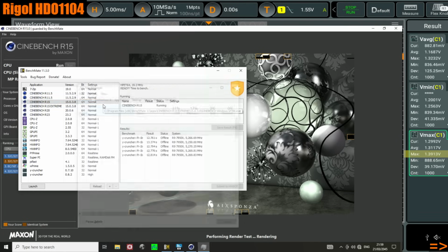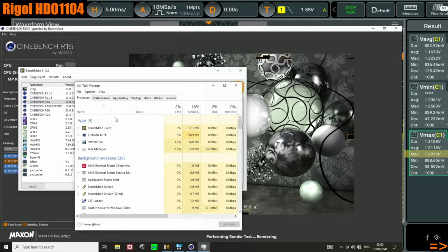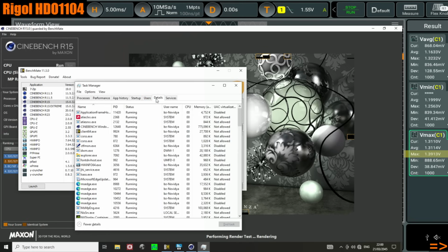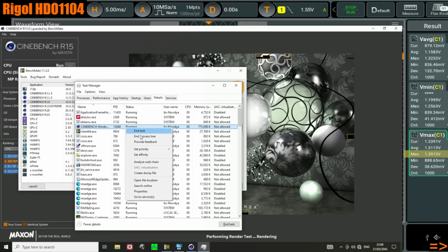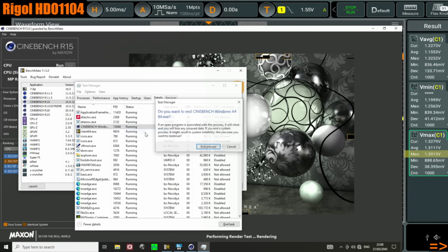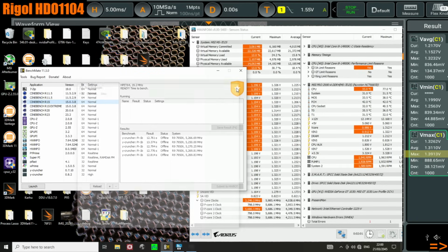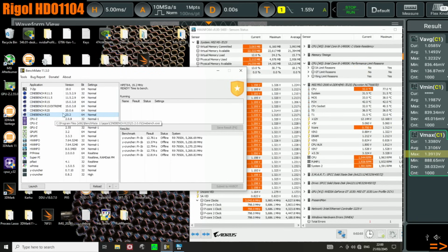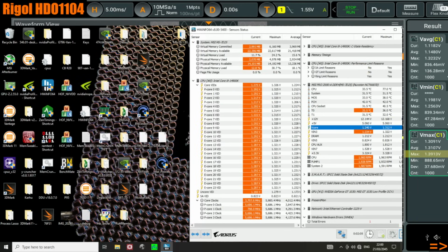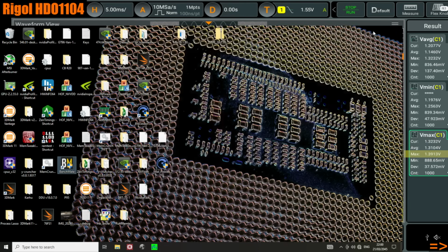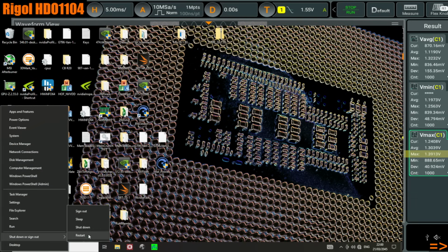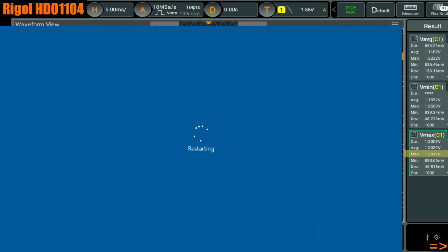The reason I'm saying that's kind of random is because in a previous take of this video, I actually managed to get Cinebench 23 to still finish even with a 160 millivolt offset, and at that point 15 froze up. And in pre-testing, I actually managed to pass 15 with like 150 millivolts at one point. So actually we're going to briefly stick 150 on there.